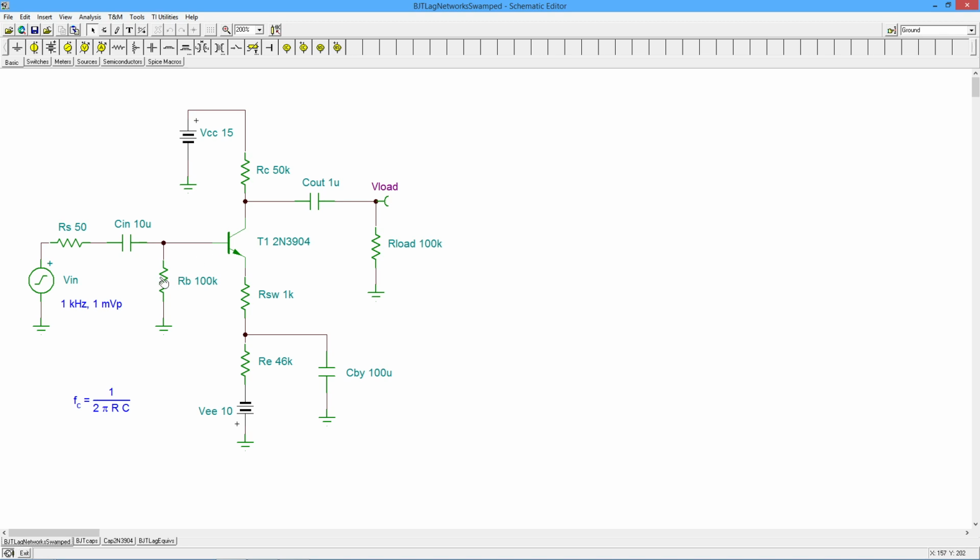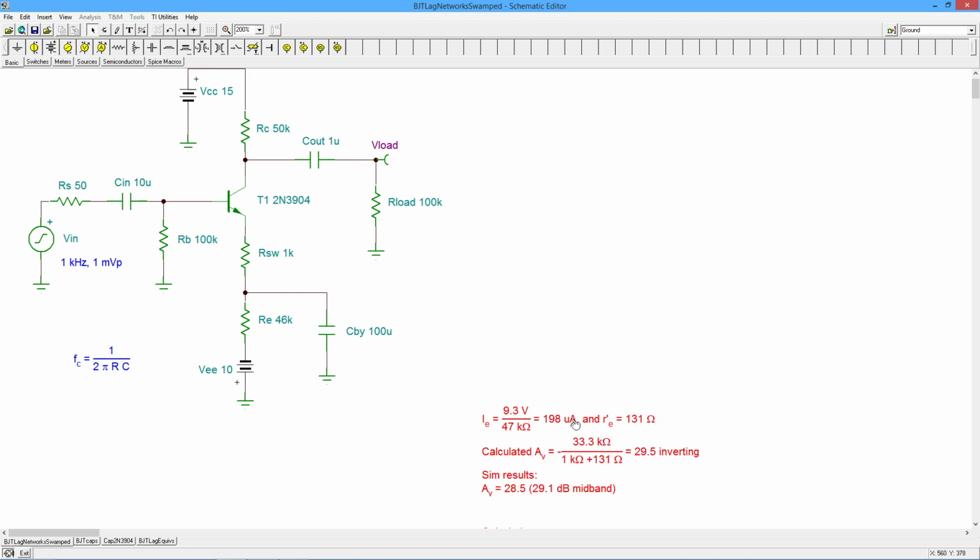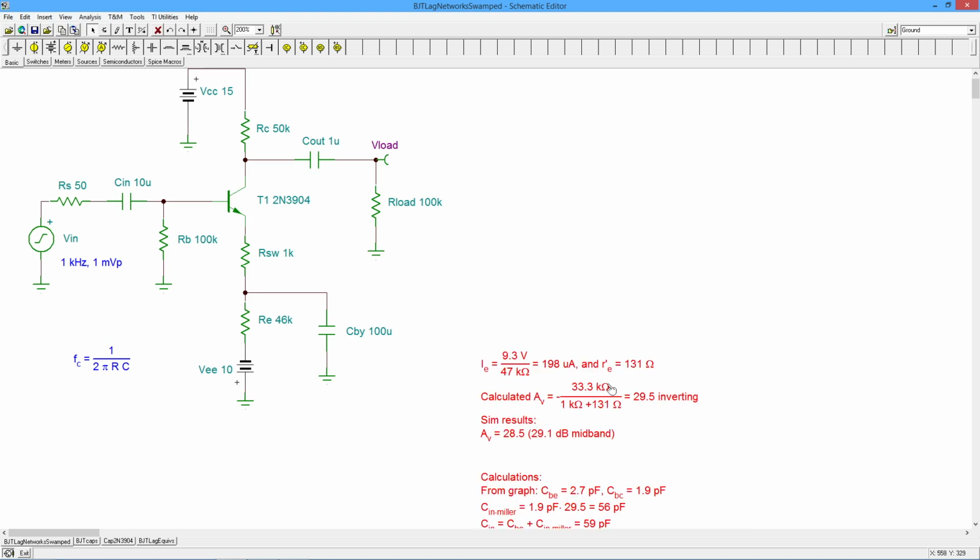Like I said, don't forget there's little capacitance associated with all of these resistors, with the wiring, circuit board traces. So, we're not expecting results that are 1% or better in terms of agreement, right? This will definitely put us in the ballpark, though. Okay, so now let's turn our attention to the simulation result that we get. I do have some calculations I'm going to pull up here so that we can see them, just to remind ourselves of what's going on with our gain and so forth.